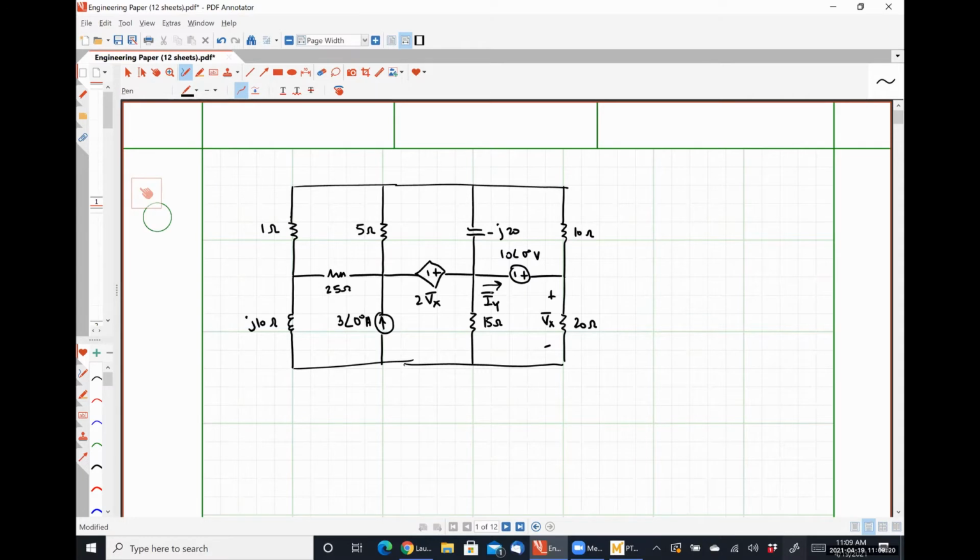So just for the sake of argument, let's go ahead and look at this thing as a nodal analysis question. We have 1 node at the top, 2, 3, 4, 5, 1 node at the bottom. So that would be 5 equations, 5 unknowns, and we would have a relationship with Vx, except that that's already one of our meshes, or excuse me, one of our nodes. So I have no problem doing it with mesh, but do you change your answer now that it's 5 equations, 5 unknowns, doing it nodal? I'm legitimately good either way, or we can do it both just for, I don't know, being tedious as hell.